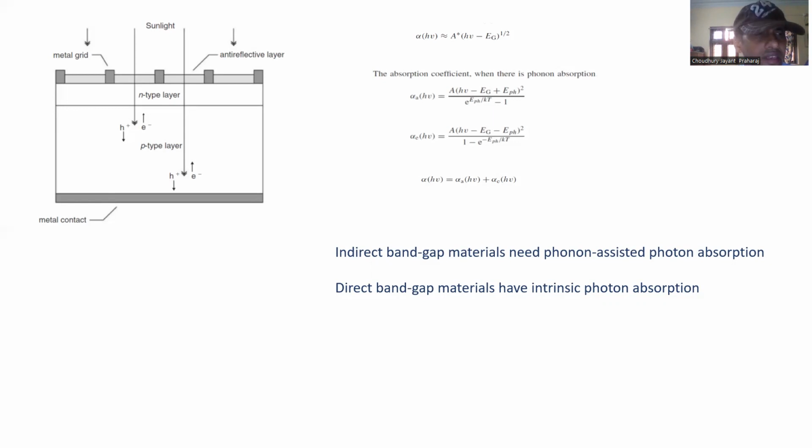One other thing is that since the indium gallium nitride alloys are getting used, we need to keep in mind that indium nitride is direct band gap and gallium nitride is direct band gap. But what about the alloys? Now, for low level of alloying, that means when the gallium percentage is high or when the indium percentage is high, you can expect that it will still remain direct band gap. But what happens at high alloying? It turns out that in these materials, it is direct band gap all the way through. This may not be the case in all kinds of alloys.